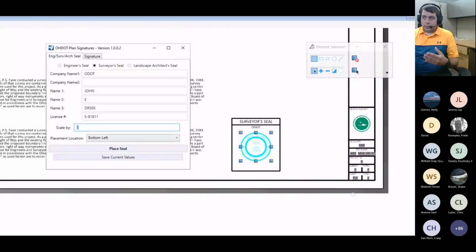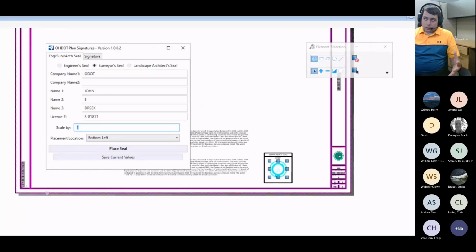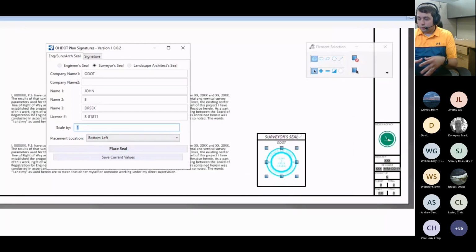If you're printing that down to half size, the 11 by 17, you're technically taking that sheet and halving the size of it, right? So that box is going to get halved, which would be too small to meet the physical dimensions laid out on the size board. That only happens if you're going to print out a reduced size page, right? If you're going to print out the full size page, what it's placing is going to be the right size. Hopefully that's clear to everyone.